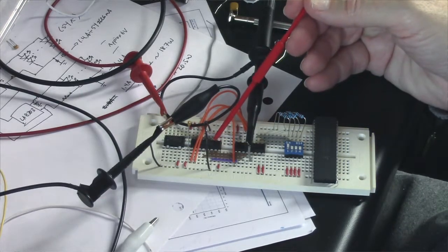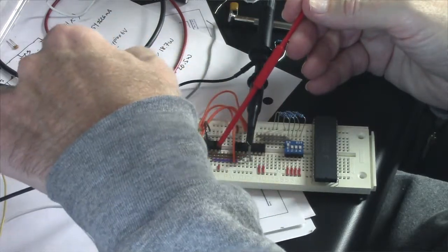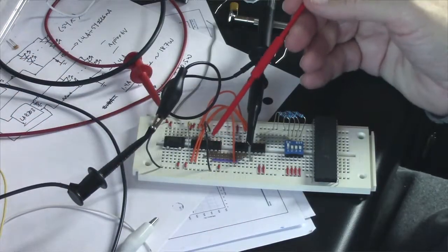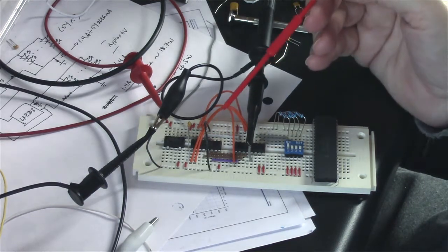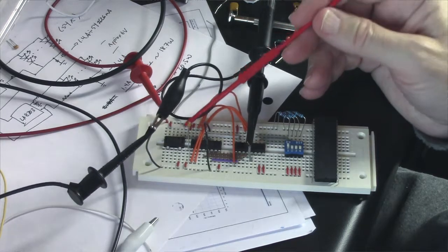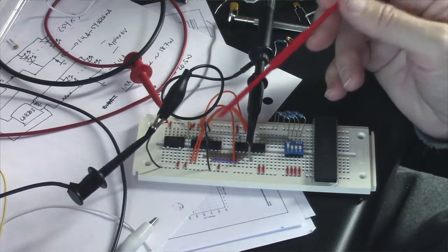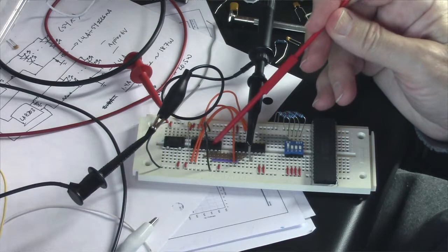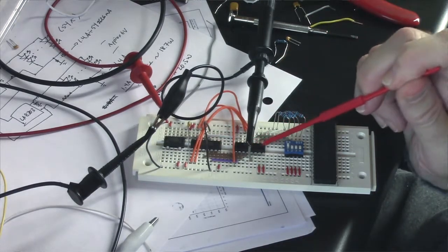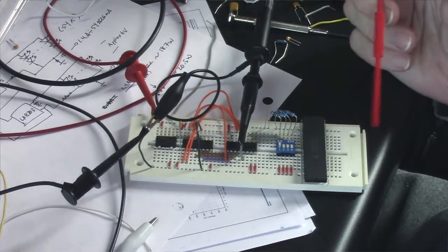This chip is basically, I don't know if you can see that or if the ground lead is in the way there on the scope, a bunch of dividers, divide by 2s. And so, as it turns out, if I use a clock of 19.6608 megahertz, then I can get all the rates I need out of this chip. And then I'm using this chip, a 1 of 8 selector, to select the specific rate I want.